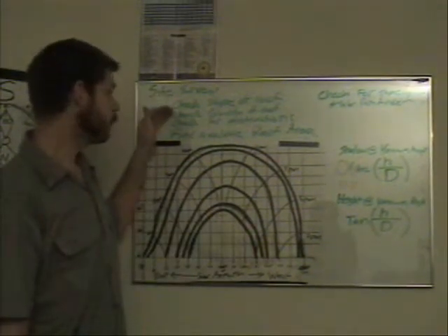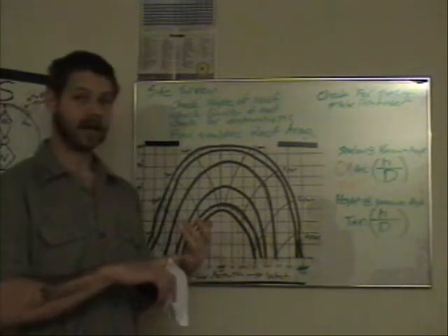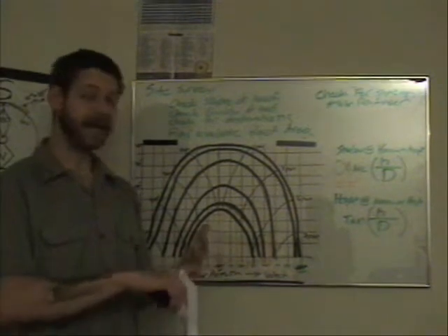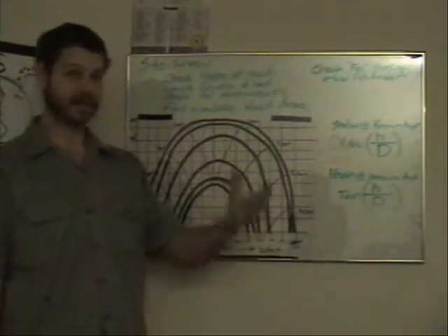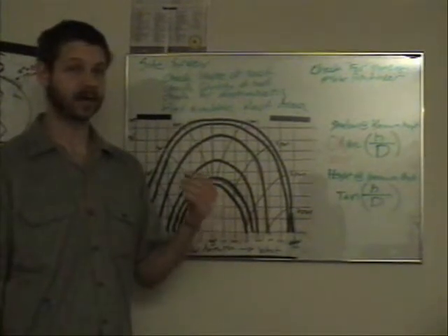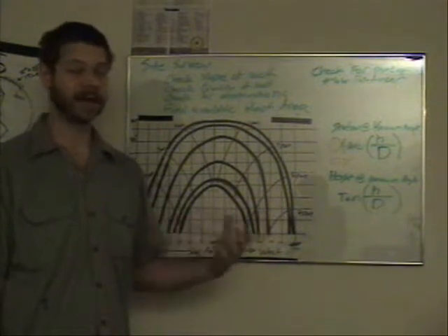Check the quality of the roof. When you check the quality of the roof, you want to check for roof deterioration, you want to check for age, you want to check for obvious slumping in the roof. If there is any kind of significant deterioration, you're going to want to call a structural engineer and make sure that that roof can carry the load that your array is going to put on it.